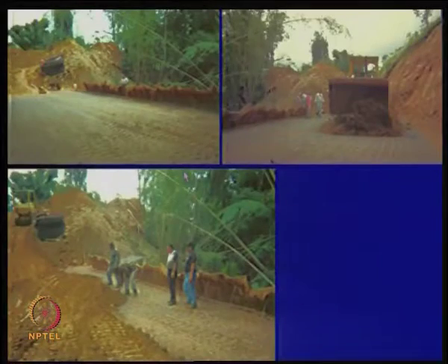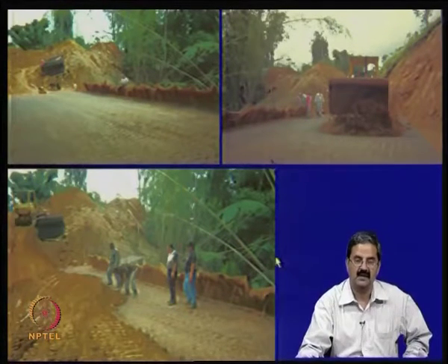In fact, in many places abroad, like in Vietnam and other places, because of not providing adequate length, the reinforced slopes and walls have failed. And even in India, there are many cases where if they do not understand the principles of reinforced soil walls or reinforced slopes well, then they are in for trouble. But it is a very efficient technique, where you can't construct a 70-degree slope normally, but because of this technique it is possible to construct, right.